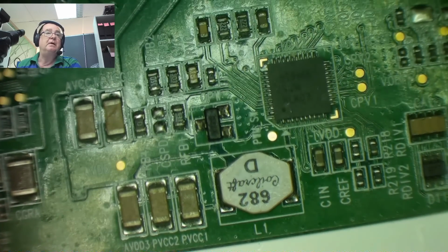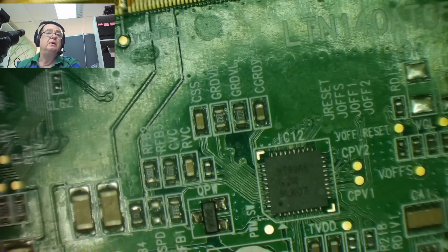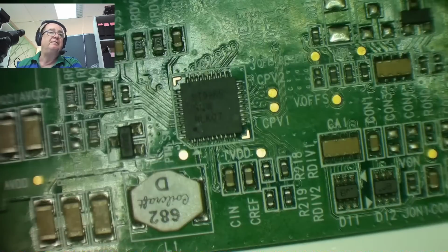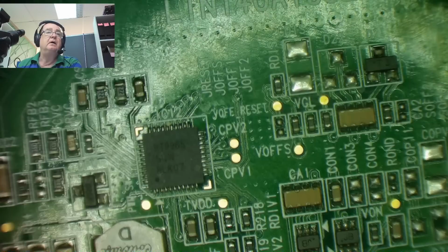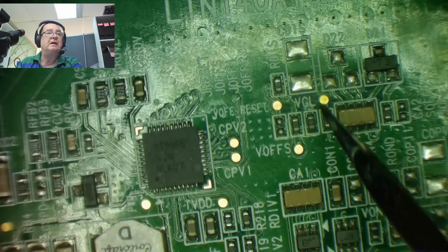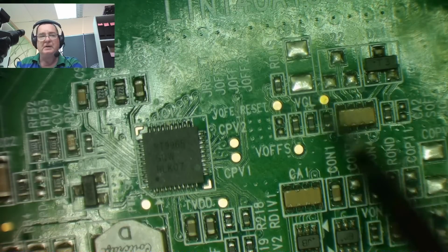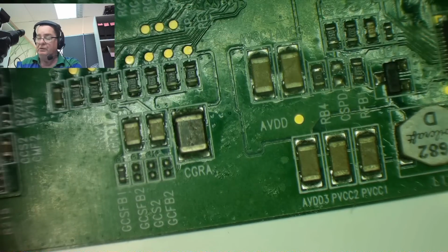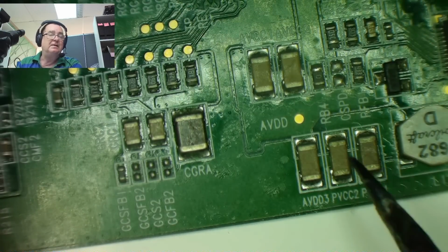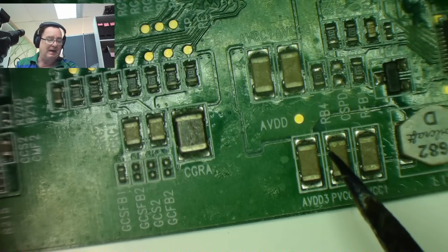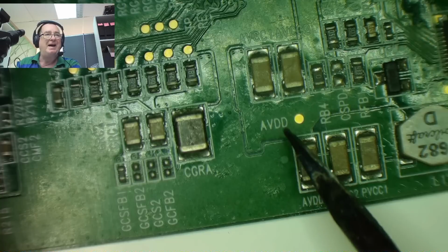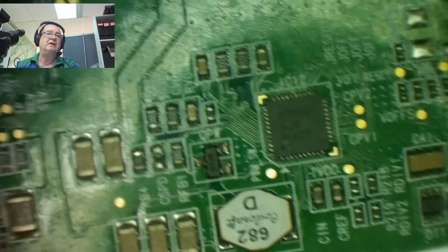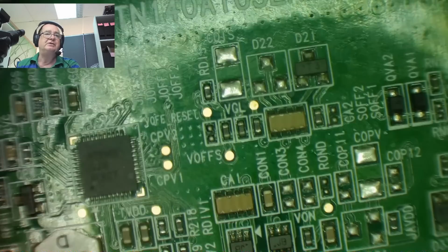Now we have on here some test points, and one of them is VGL, and we've measured it before. Where are you now? Yeah, so VGL is here. It's minus 6.9 on both boards, and it kind of matches what that information is giving us. Also here is another one of the voltages we were interested in, AVDD. That information is suggesting it's going to be about 10 volts. We have 7.98 on here, so 8 volts, but again, it's the same on both boards. So that's 2 of the voltages. What I can't see is VGH, which that information suggests is going to be about 16 volts.